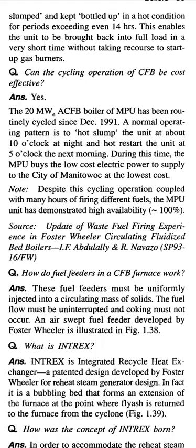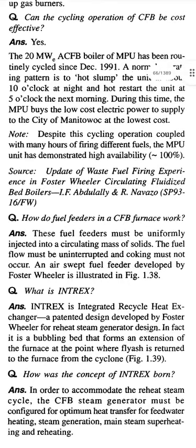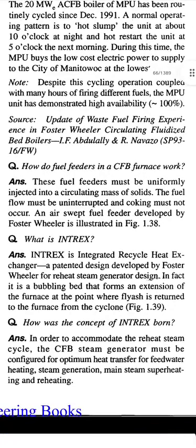Question: How do fuel feeders in a CFB furnace work? Answer: These fuel feeders must uniformly inject fuel into the circulating mass of fuel solids. The fuel flow must be uninterrupted and coking must not occur. An air shaft fuel feeder developed by Foster Wheeler is illustrated in the figure.